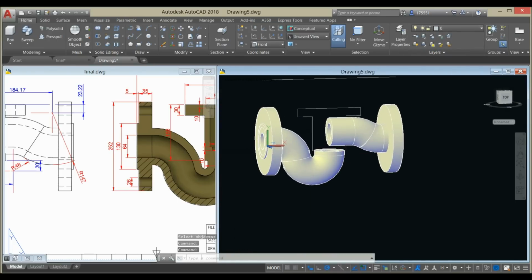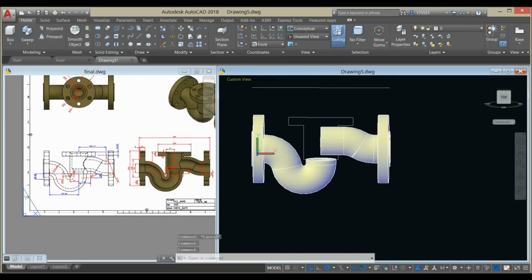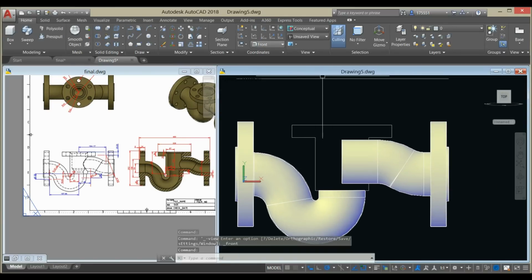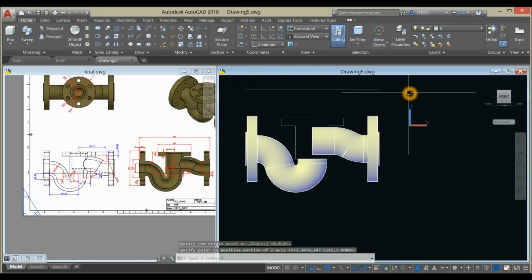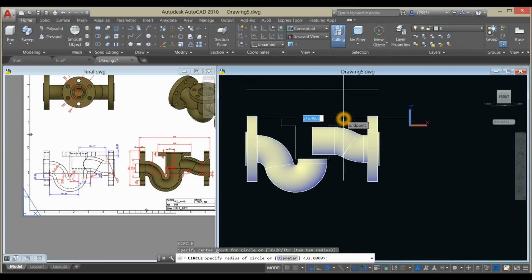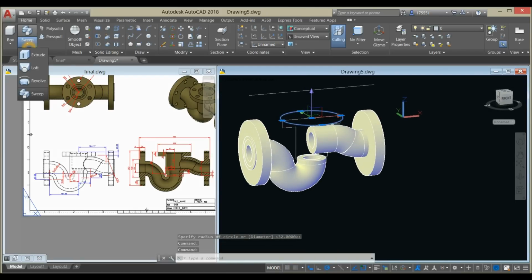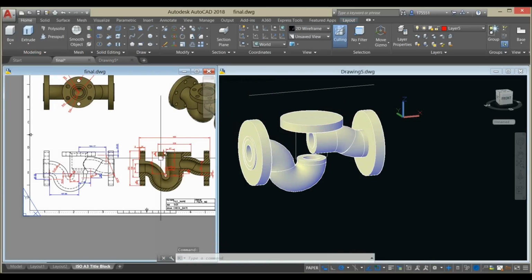The next thing to draw is this one here, this flange. I'm gonna change the direction of my z-axis vector and point it upward. So this is the direction of the extrusion, or downward, doesn't matter. So say for circle, click that midpoint and just snap that in point. So if you press shift and the wheel of your mouse at the same time, you can see this circle, and extrude this one downward and just hit that in point, which is 30 units. So this one here.